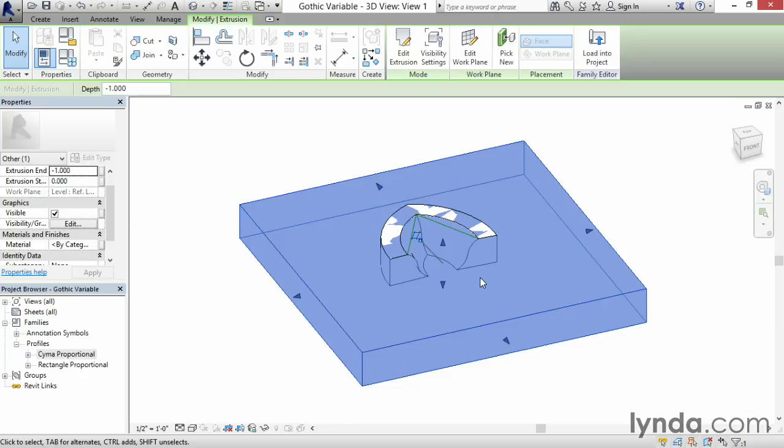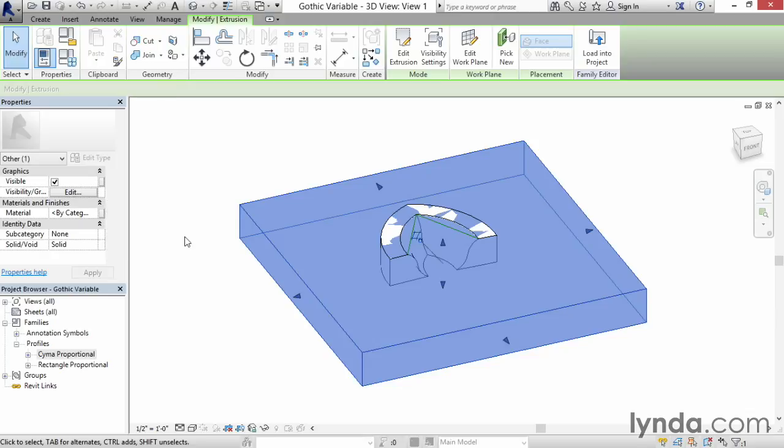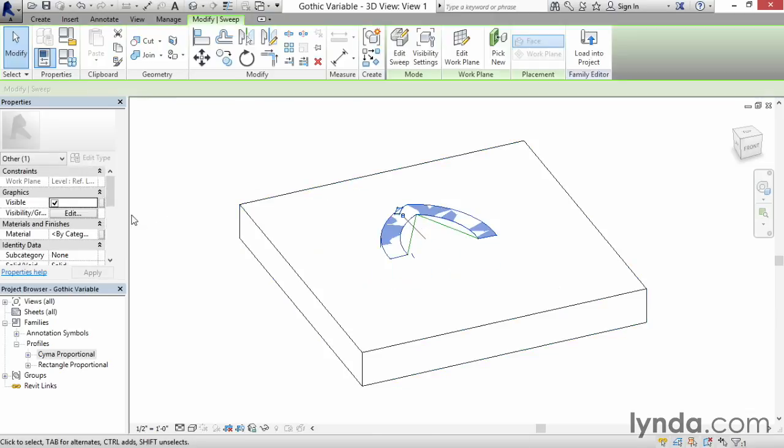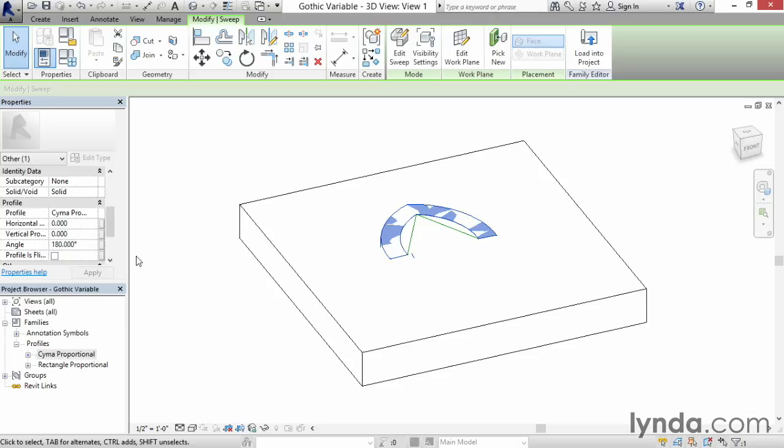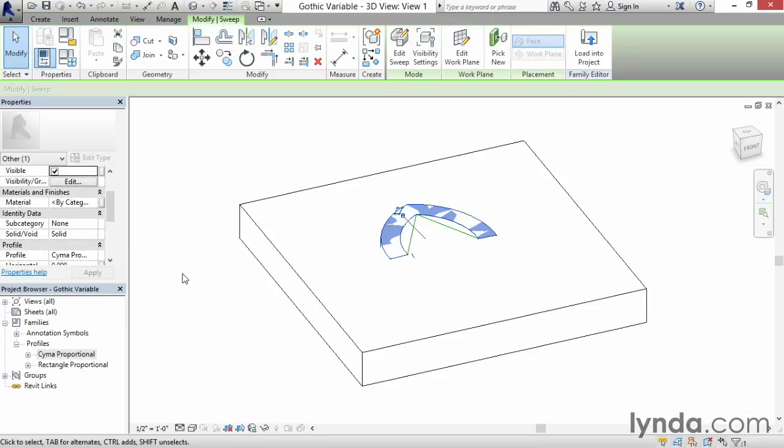So if we wanted to cut a hole in our wall or our surface and embed this molding inside that hole that we cut out, then that would be an appropriate orientation. But if we want it to actually project away from the wall, then we might want to adjust that. Now, we certainly could fiddle around with some of the additional settings here and look at the vertical offset, for example, and we could start manipulating that. But what I'm trying to avoid doing is having to add lots of extra parameters. So I'm going to go with a much simpler solution to solve that problem.